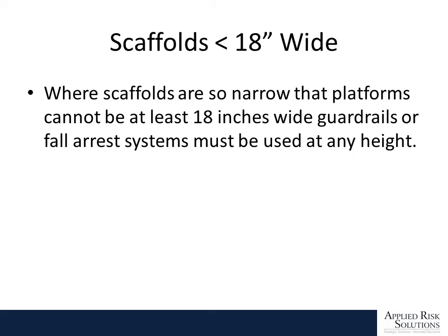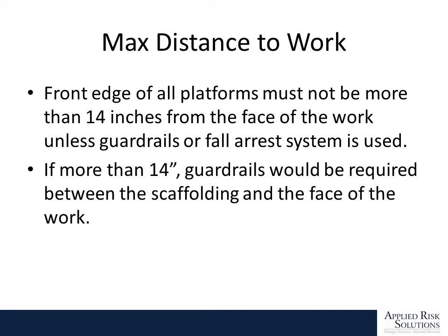When you're working on scaffolding less than 18 inches wide, it does not matter what height you're at, you must have personal fall protection or guardrails, one or the other.